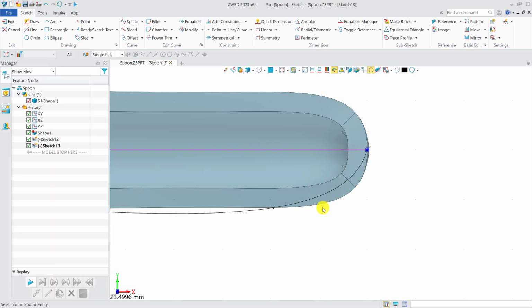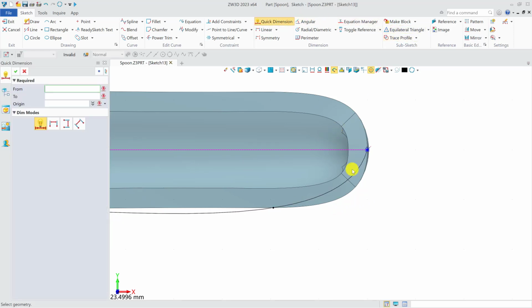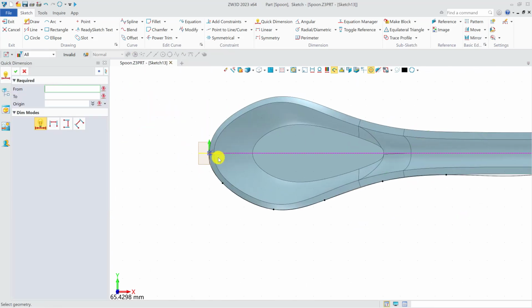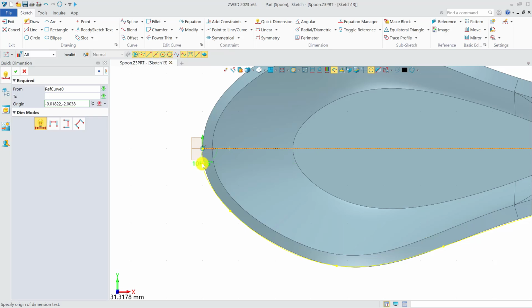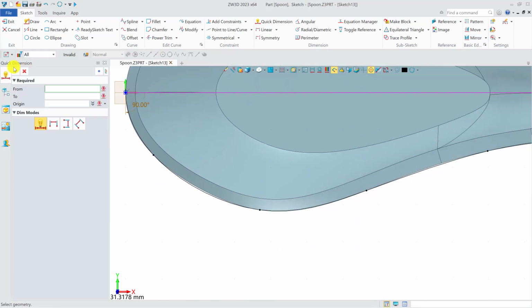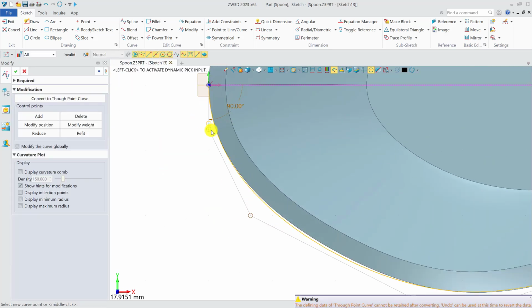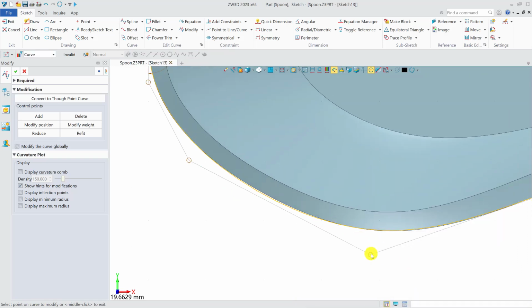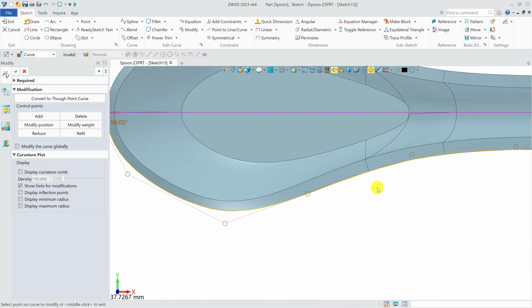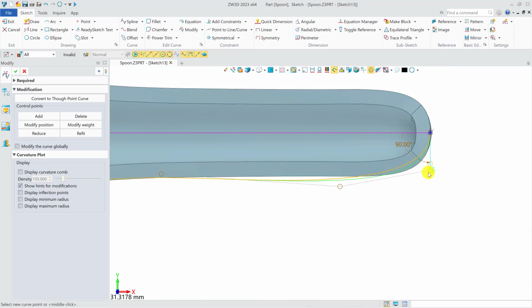And the other key point is that we need to set the 90 degrees on the start and end points. If not, there will be an obvious line in the mirror junction. Because we need to mirror the shape in the end, it will affect the appearance quality. After setting the 90 degrees, we adjust the points. We need more patience to adjust it.